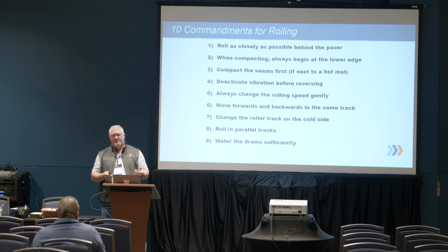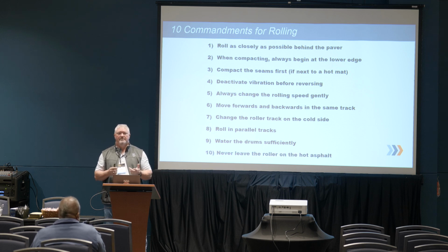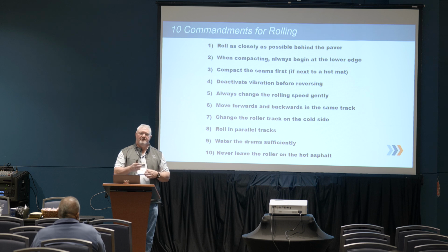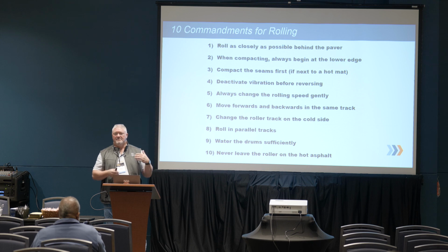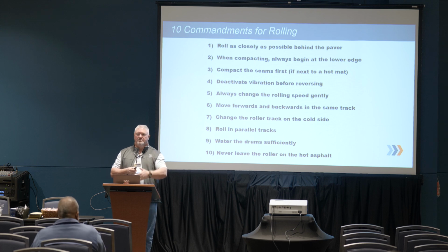Water the drums sufficiently. I only need enough water on there to keep from picking anything up. Never leave the roller on the hot mat. So many times I see when the paver stops, that breakdown roller's right behind the screed. If you're going to be behind the screed, at least stay on an angle. If you have any chance at all, get off on a cold mat. Or back up to where the beginning of your pass is and sit there. It's a little cooler, less chance of putting dimples in there. And let the other rollers go by and finish their rolling patterns.